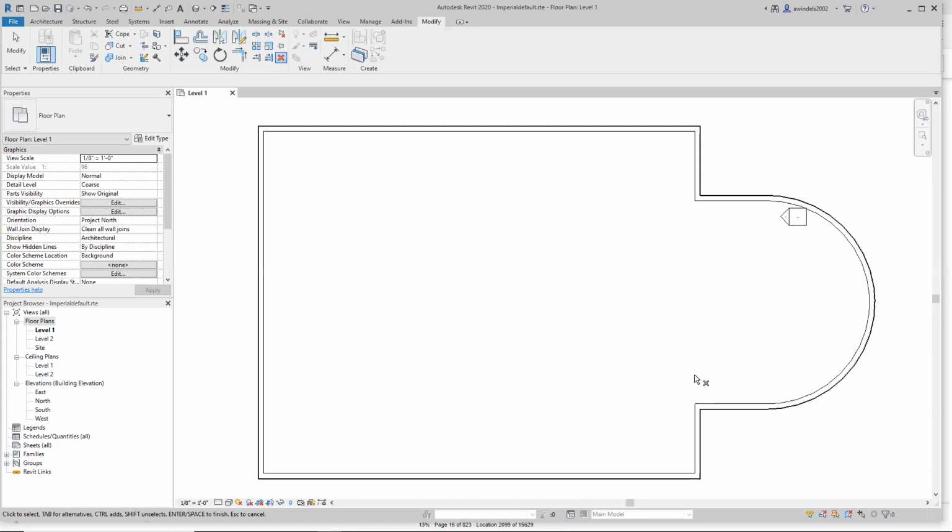Okay, back to page 23 on chapter 1. We're going to talk about view control and object display. So going down to the view control bar down here, boom, it's different graphical views of your model. And this is very important to understand that each view, each area, you can control how things appear differently between one another in each of these views. They're independent of each other, how they look.